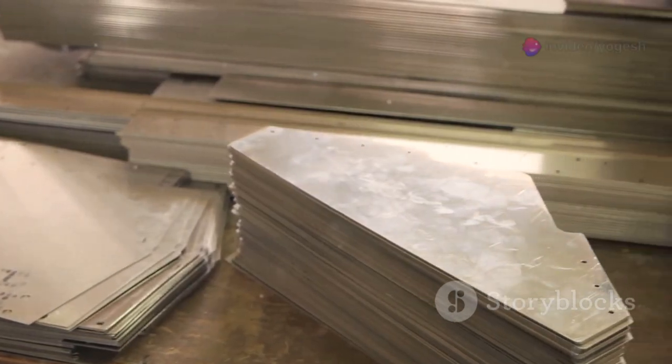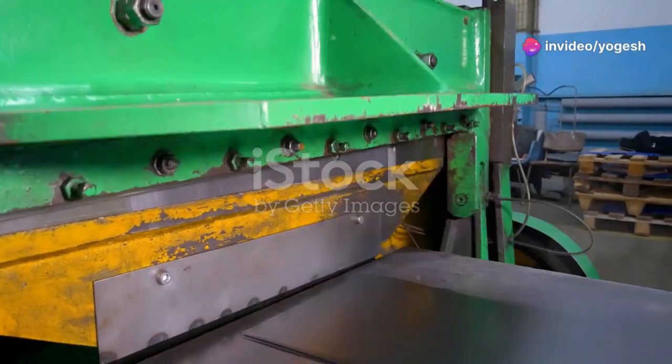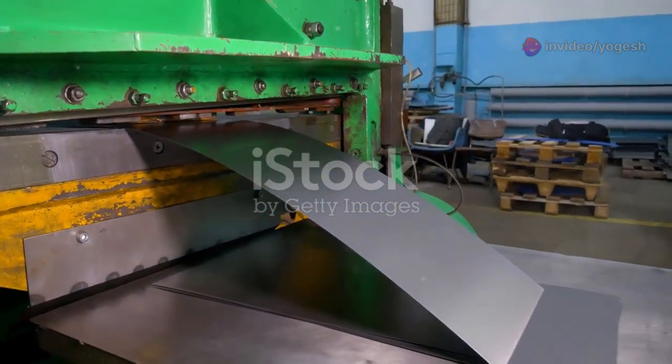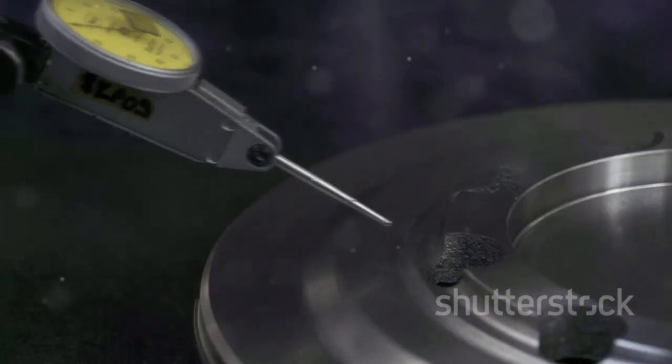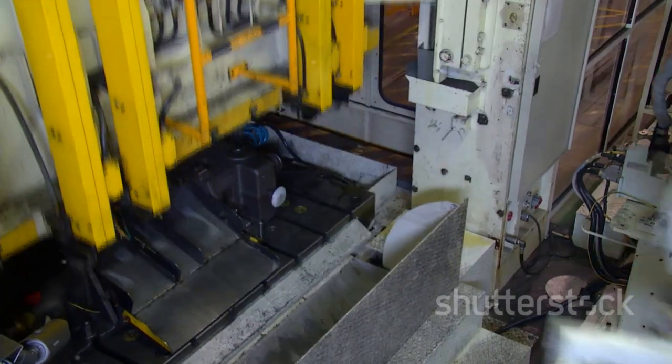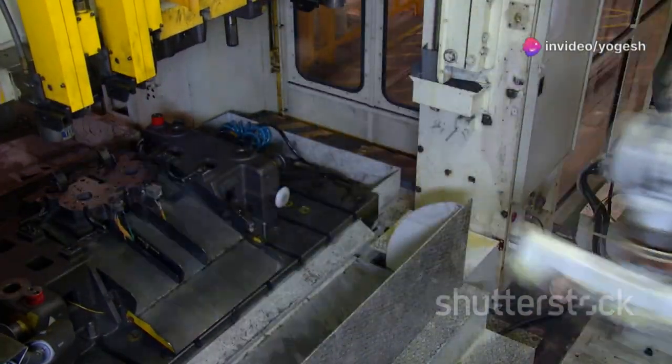Always use a uniform thickness. Sheet metal starts as a single, flat piece. All operations, cutting, bending, punching, assume the same thickness throughout. If you need different thicknesses, design separate parts and assemble them.